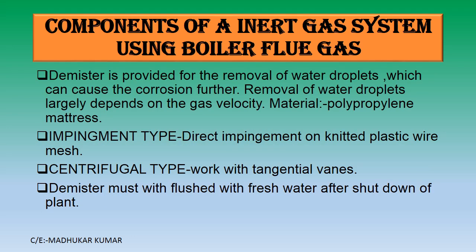As we have seen already, the demisters are provided for the removal of water droplets, which can cause further corrosion if the water is not removed. Removal of the water droplets largely depends upon the gas velocity, which is also one of the factors. You have zigzag type polypropylene matrices fitted, through which the IG has to pass, and the water droplets stick to this material, and the IG passes over and these water